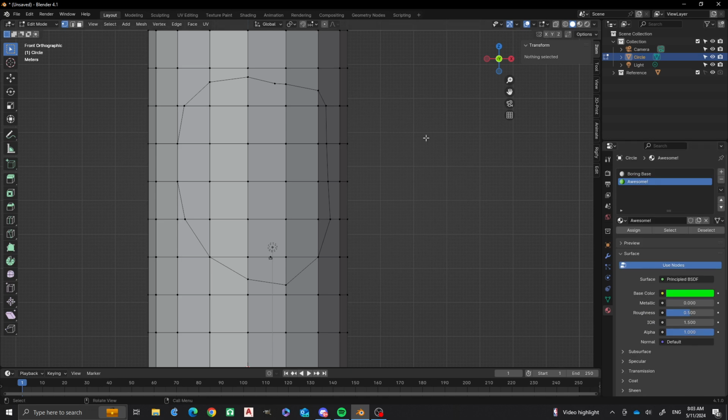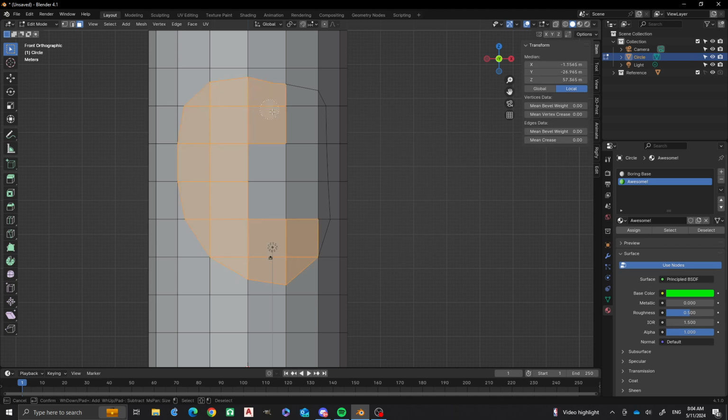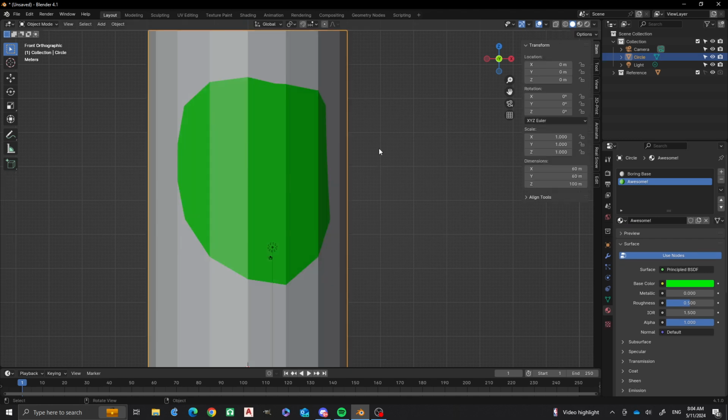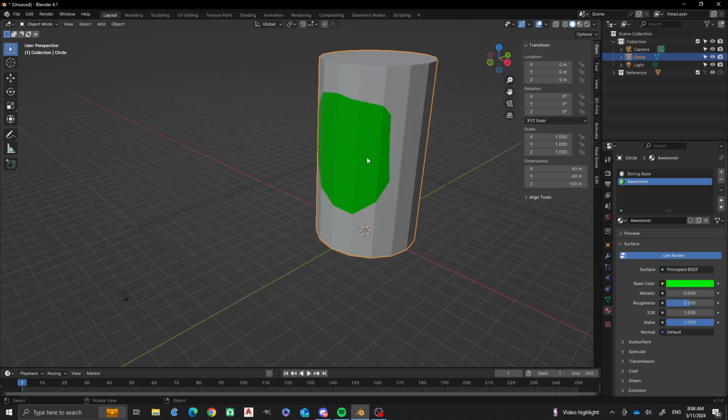And now I'm going to change to my face selection mode, 3. Okay. And then I'm going to take C and select those faces that I just made in that island. Okay, escape from that. And now we're going to assign, and there we have a material selection. And then this is where the fun begins, right? So I'm going to tab out of edit mode, and we can do a few things with this.